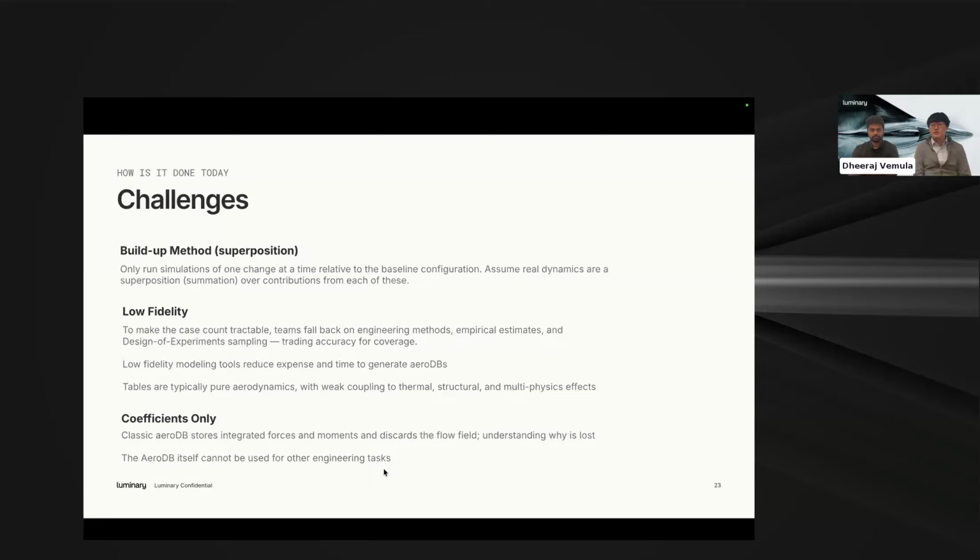There are some low fidelity tools, mostly based on polynomial fits, sometimes a little bit better with nonlinear regression. But at the end of the day, all they are doing is giving you some coefficients. And we already know from our experience that these types of coefficient mappings don't do very well when you get to a really highly nonlinear regime. You really do need to do the full prediction on the surface and integrate from there to get a good estimate of what those coefficients would be in a real flight.